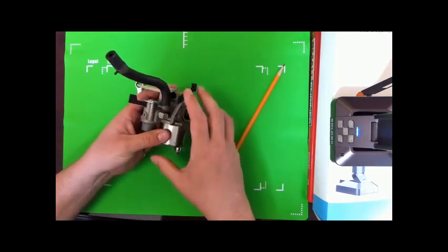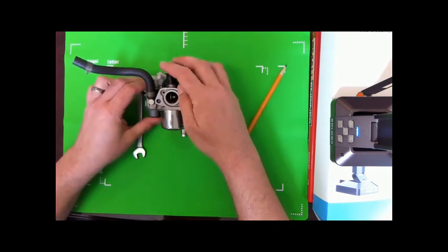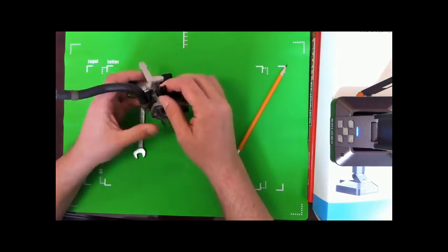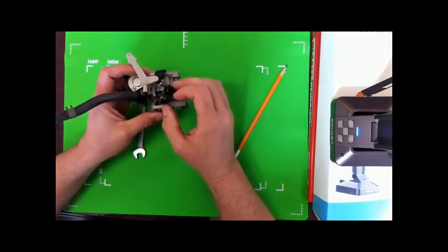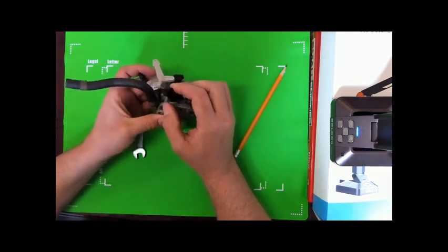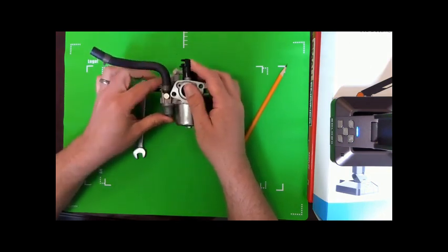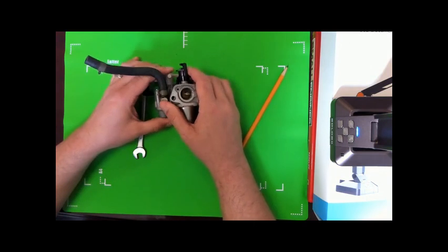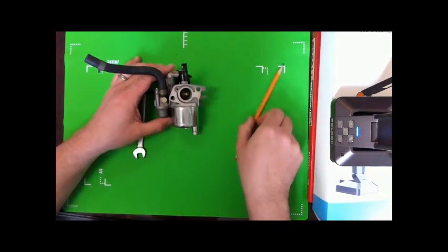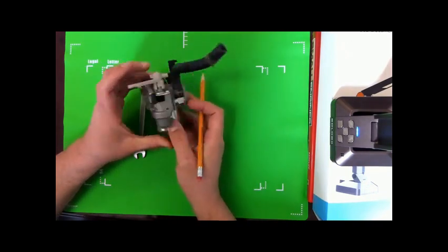The fuel line is coming towards you, and you can see the hose clamps. If we go on this side, we'll see a similar butterfly. This is actually the throttle side, so that's a throttle plate. This particular engine doesn't have a throttle cable that we would manipulate manually, such as maybe some of our walk-behind lawnmowers. This is going to have a throttle spring, more tied in with our governor to keep the engine running at a constant RPM, more of a generator type of capacity. And we see the back end of one of the jets here.